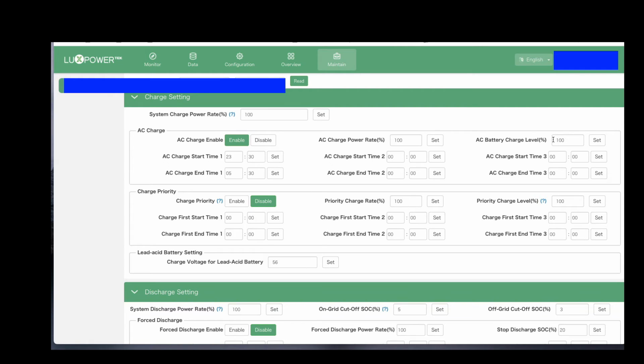If you have a good size solar system and you know that you can produce a lot of power from the sun, what you don't want to be doing is filling it up with grid energy, only for it to be exported when the sun is shining. So in the winter periods, you can set this to maybe, I don't know, 60%, 70%. Everybody's different, depending on your orientation.